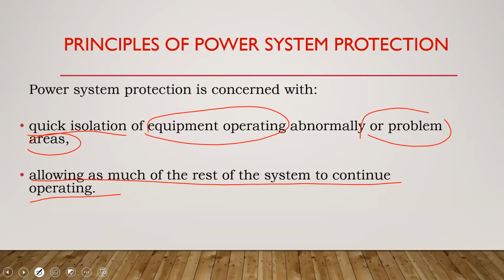Now, if that breaker is faulty and doesn't trip, and the whole house goes, in the same way, if I am unable to isolate the faulted section or equipment in my power system, it is going to cause the fault to what we refer to as escalate. So it's going to take out more or a larger area than need be.